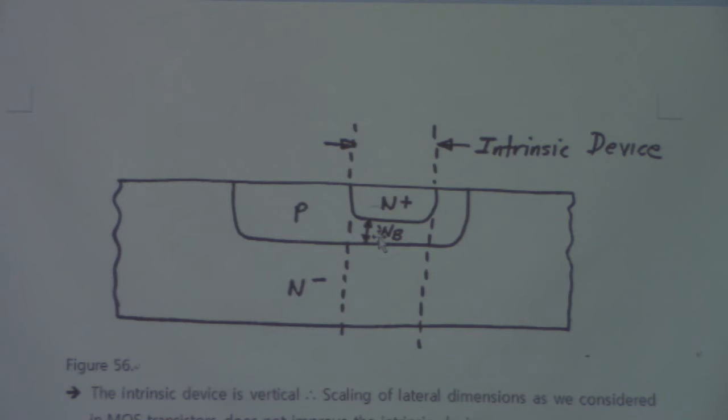In order to have a small gate length, we also have to change the vertical section, like junction depth, gate oxide thickness, and the dopant concentration, things like that, which is related to the vertical scale. If you want to change the scale in the lateral dimensions, you also have to change the scale in the vertical direction in order to keep the electric field constant.